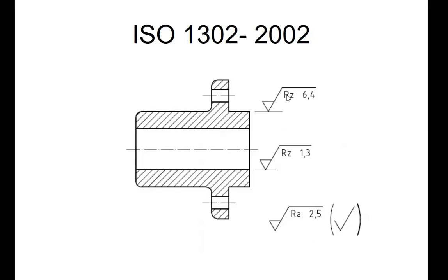But today, it is the place to write the roughness height. So to be able to notify the reader that it is not a cutoff value but a roughness height, the preceding symbol today is very valuable. If there is a number preceded by such an abbreviation, this means it is not the roughness cutoff value, but the roughness.